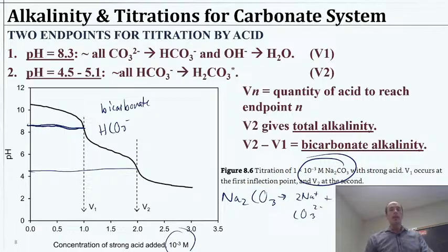And that also comes from when we talked about the net strong base stuff, where we took all the cations, the electroneutrality balance, where we had the non-pH related stuff, all the strong base cations and strong acid anions on the left, and what was on the right was the carbonate species and any other buffer, any other weak acid. So if we just have a carbonate system, that's the strong bases and cations on the left, and the carbonate system on the right. And that's our alkalinity. Okay.